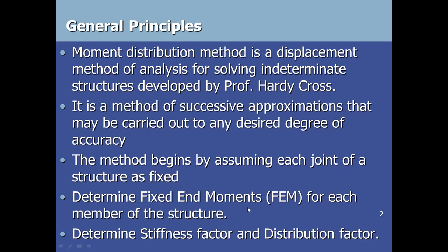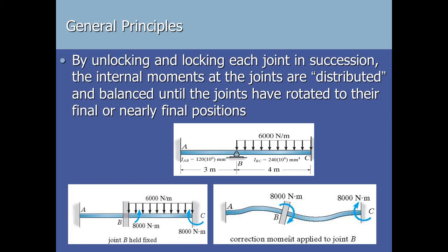Determine fixed end moments for each member of the structure from the table of fixed end moments. Then we determine the stiffness factor and distribution factor for these members.